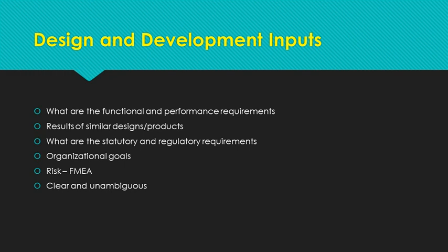Here is an effective point to perform a failure mode and effect analysis, an FMEA. The FMEA is an input before the design process starts. The FMEA should be reviewed at each design review to see if the current ratings are still valid and if additional risks should be considered.